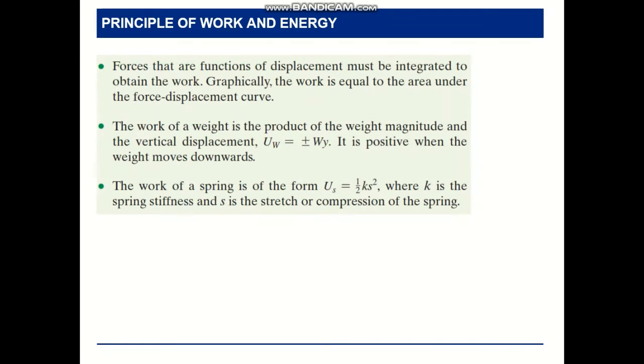If we keep moving, forces that are functions of displacement, so if it is F of s, we need to take the integral, right? It must be integrated to obtain the work. Graphically, the work is equal to the area under the force-displacement curve.